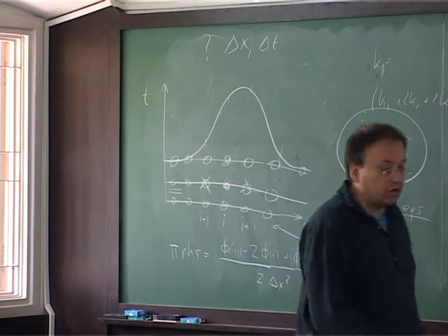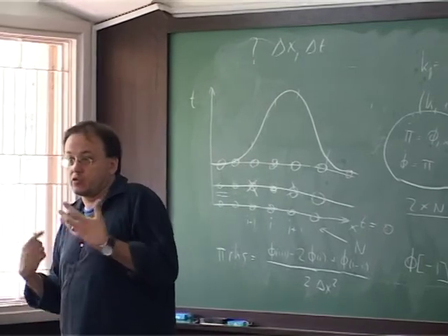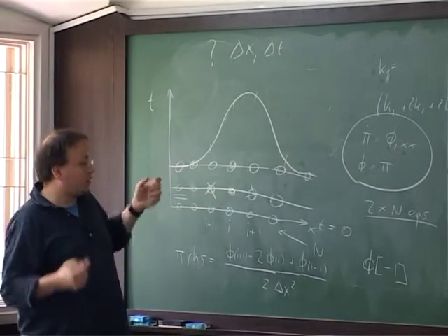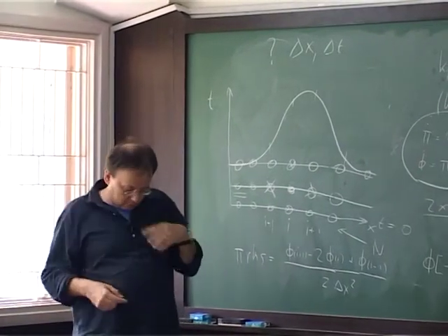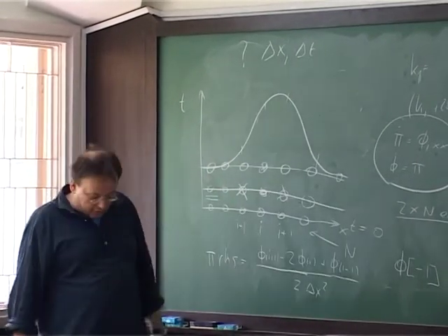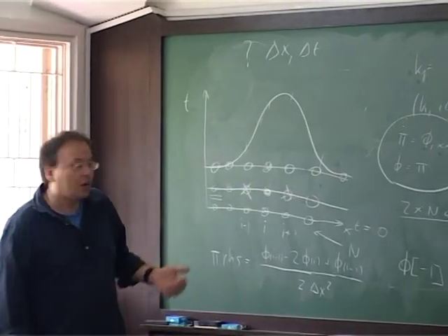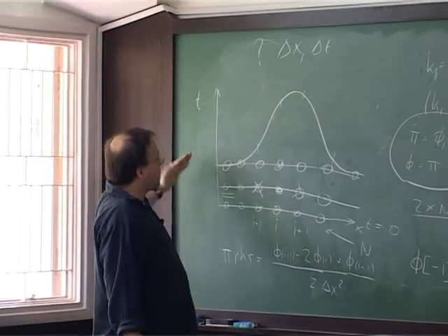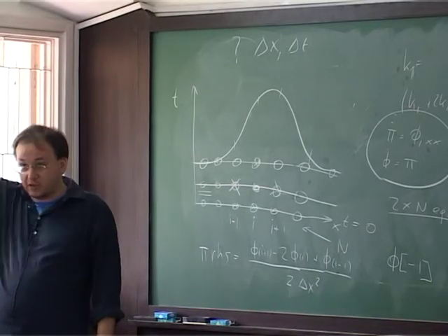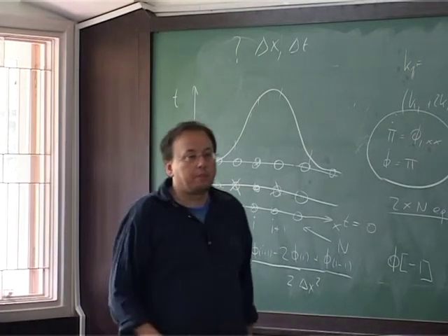what's the actual resolution that you need? You have to find that out by the convergence test. You do the convergence test, and when you get the expected result, you know that your grid spacing is small enough that you can approximate the solution. But there's certainly a necessary condition for how small delta x should be, which is easy to say: the function has to be recognizable, has to look nice with the sampling of grid points that you use. Probably the question is also about how large delta t.